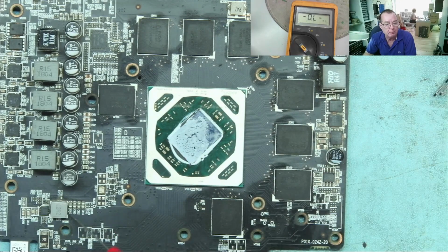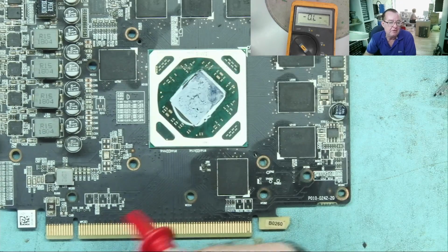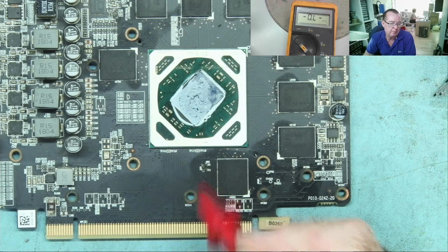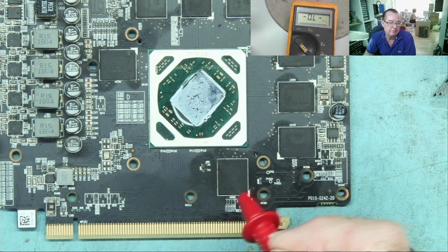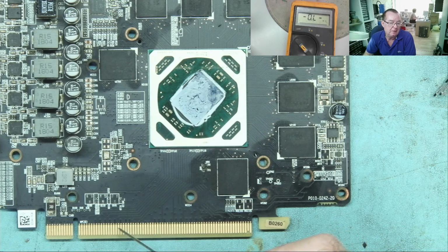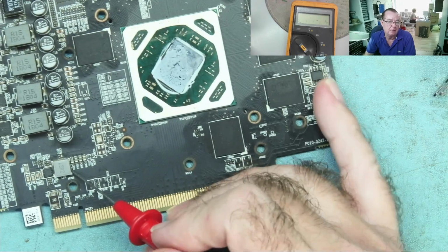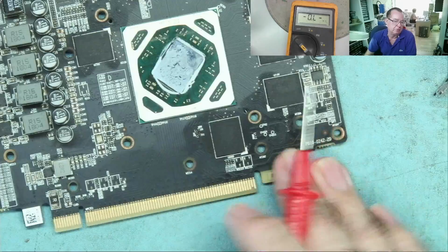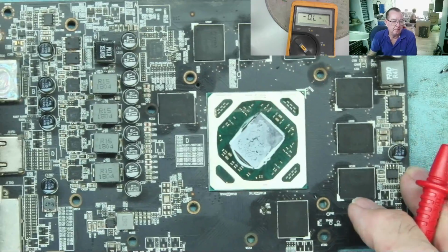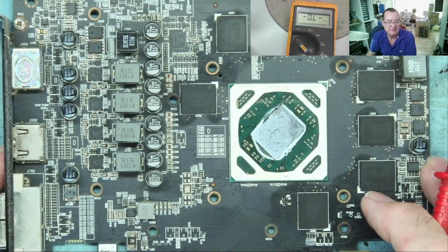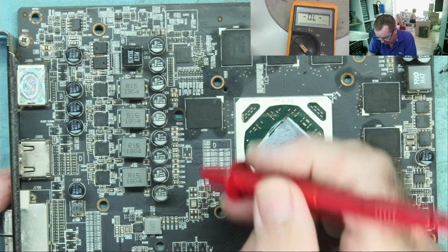But this voltage rail, PEX, the only place it goes to is the GPU. And it powers the part of the GPU that is talking to the PCI. We notice ourselves, apart from some capacitors on the other side, it doesn't really go anywhere else. So if we have a problem with this voltage rail, the chances are it's a faulty GPU. I say chances are, it's worth investigating.